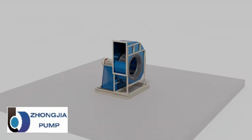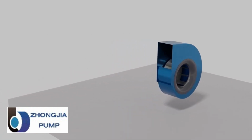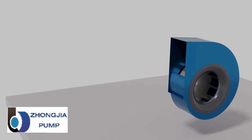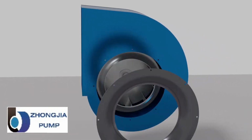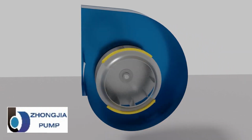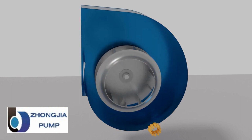Now we will see the working principle of centrifugal fans. In a centrifugal fan, the operating principle is a combination of two effects: centrifugal effect and deflection of airflow by the blades. Centrifugal force is the apparent outward force on a mass when it is rotated. Here the air entering inside the impeller experiences the centrifugal effect, and it will be pushed outwards.